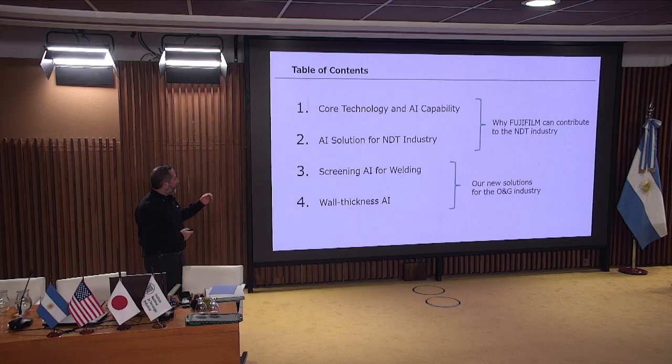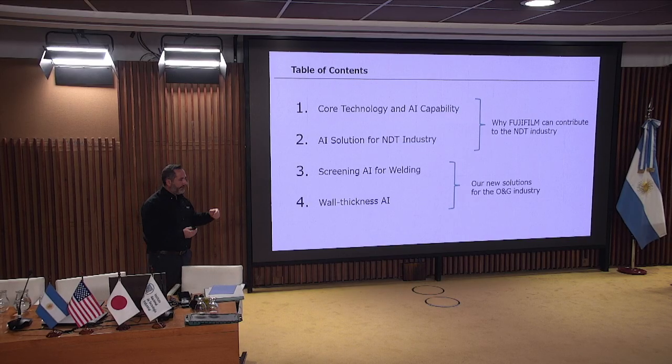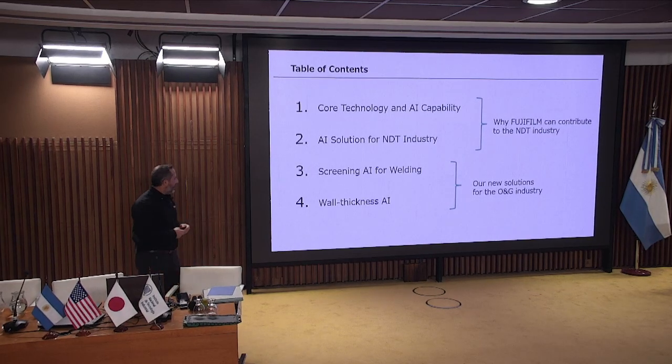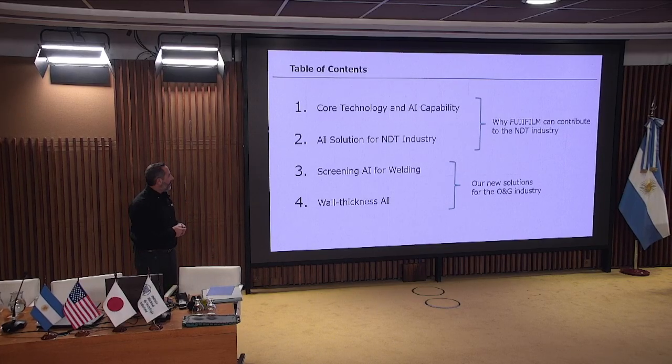So we've been doing a lot of screening for AI with welding radiographs, looking for particular flaws in welds, porosity, incomplete fusion, lack of penetration, and then also wall thickness, which is for corrosion. We've been working with AI on that.